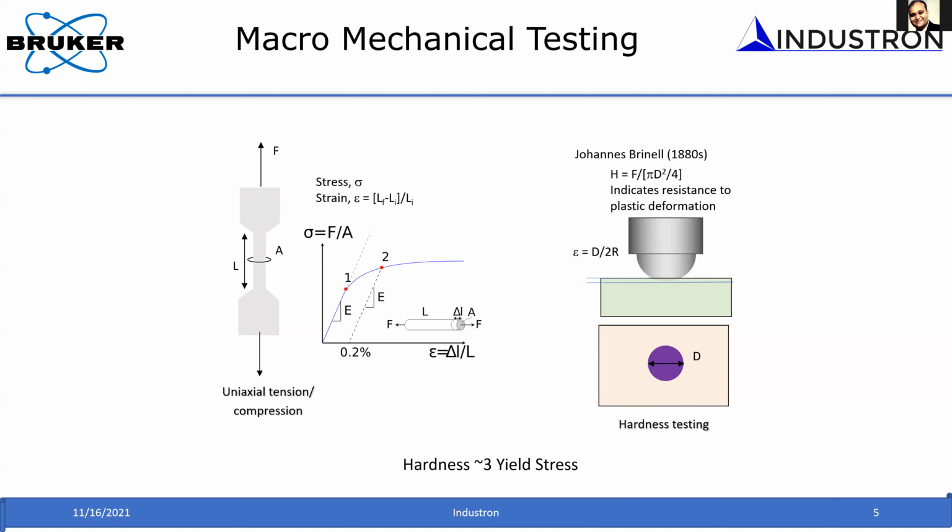Tensile testing is basically a uniaxial test: you apply stress along an axis and measure the response. Whereas when you indent on a semi-infinite plane, there is a constraint from the surrounding material as you press and try to deform the material. Because of the constraint, it finds much more resistance. That is what gives you 3 times the yield stress.